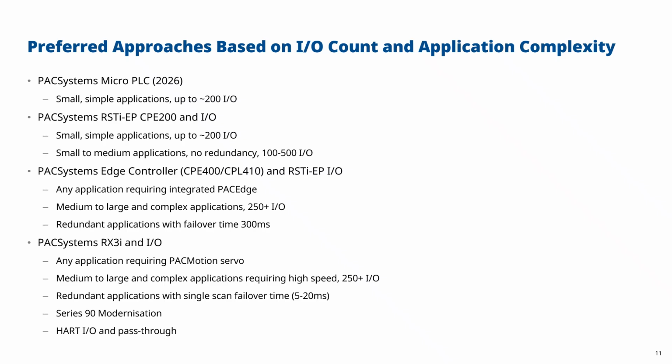The difference is that you have to use the MTP function blocks, so they're maybe going to use a bit more memory. And you would also have to think about using the correct programming software. You'd need PAC Machine Edition Pro Plus software, which is the one that's required for integrating the MTP function blocks and doing the XML export into the DCS system.